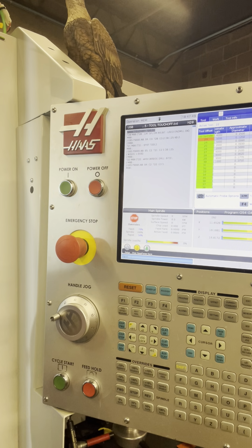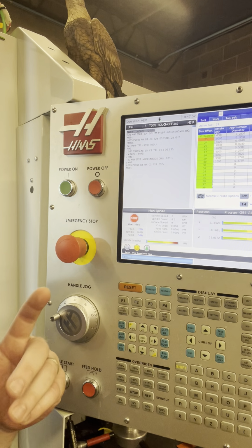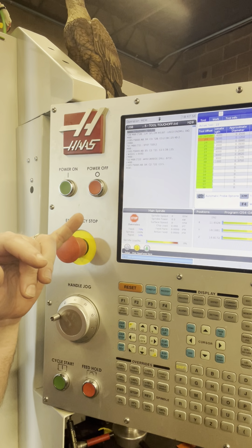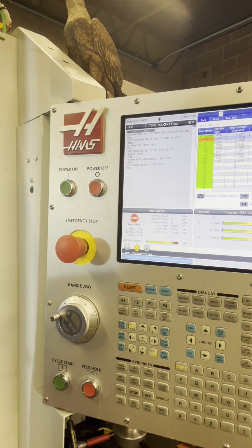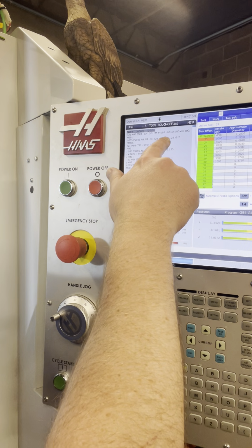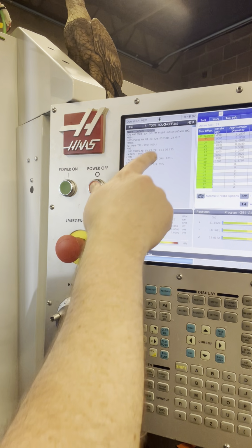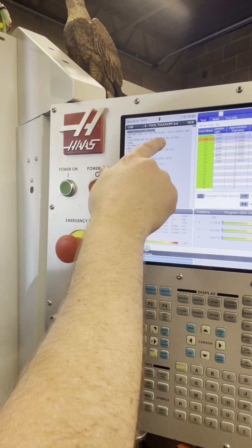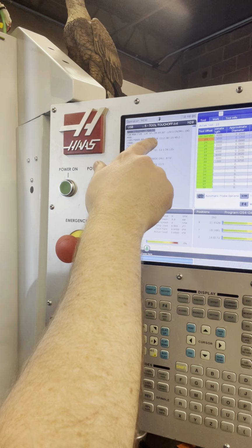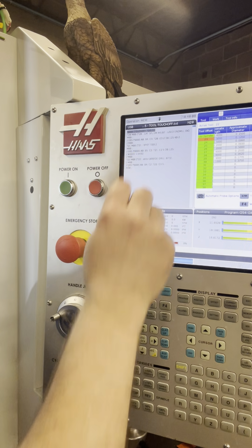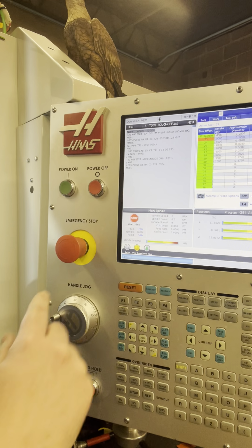And I have a little cheat sheet here for you guys. I can share that online too. It just tells you what everything is here. So your approximate radius, we use radius at RAM. You're using diameter here, so this would be the diameter. The D is that diameter. The E is the approximate length. The K is how far up on the tool to pick up the diameter.